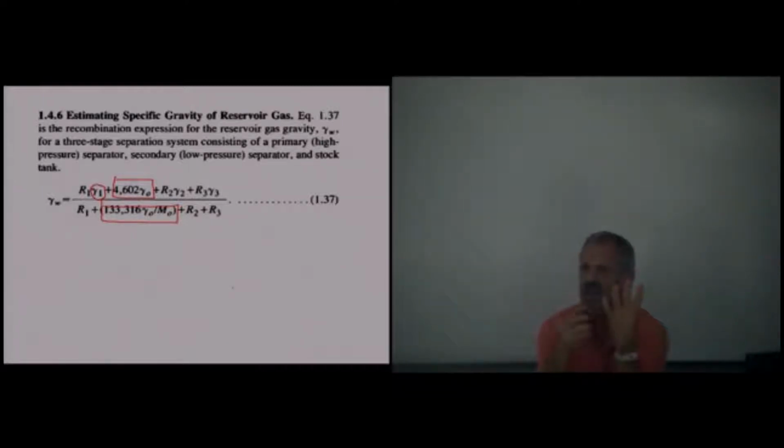So I'm not only adding 3 gases from 3 different separators together to try to get a mole balance. I'm also adding a 4th product together. I'm adding the oil. That oil and those 3 stages of gas at one point in time were gas.